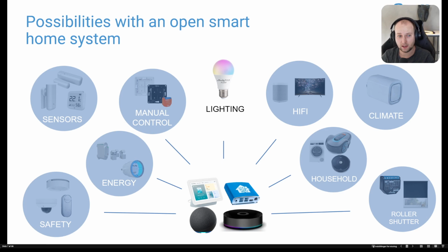And it works just fine, but to be honest, there's always someday you have to change batteries, and there's always a bigger risk of failure when you base your installation on wireless communication. Wireless communication works just fine, but in my opinion, it should be a second option. So if you're doing new installations or renovations, I recommend to do hardwired installations, but then you still have the option to reprogram and to change the functionality of your wireless switches and buttons.